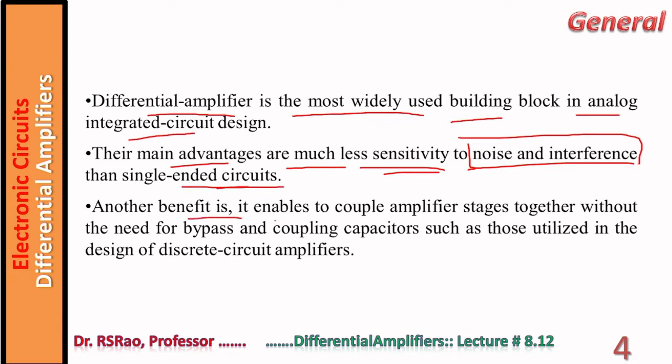Another benefit is that it enables coupling of amplifier stages together without the need for bypass and coupling capacitors, such as those utilized in the design of discrete circuit amplifiers. So bypass and coupling capacitors become redundant in the design of differential amplifiers.